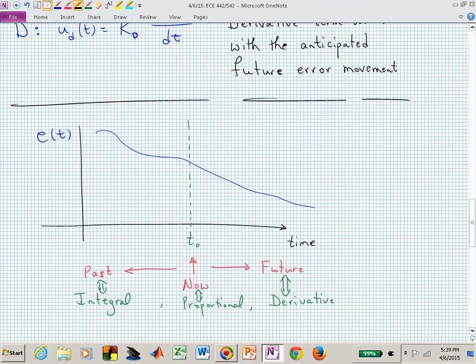We will get into, before the second exam, a PI controller. Not a private investigator, but a proportional integral controller, where the derivative term has been set to 0, and a PI controller is usually selected to improve steady state accuracy. It may slow down the system a little bit, but you're really worrying about your steady state error with a PI controller. If you're trying to change the transient behavior after you've reduced the steady state error, maybe you put in a derivative piece, and now you use all three terms. You have a PID controller.